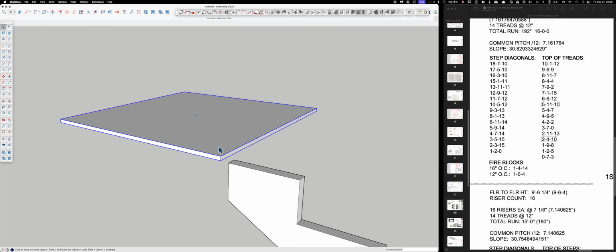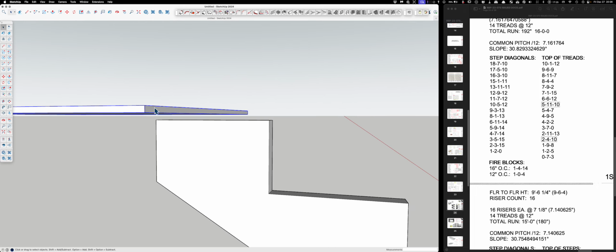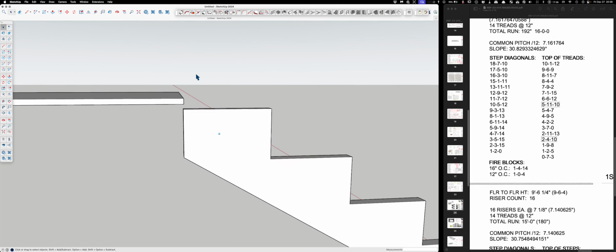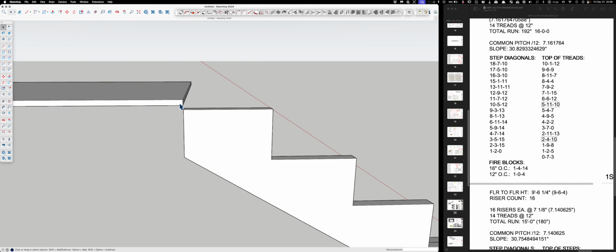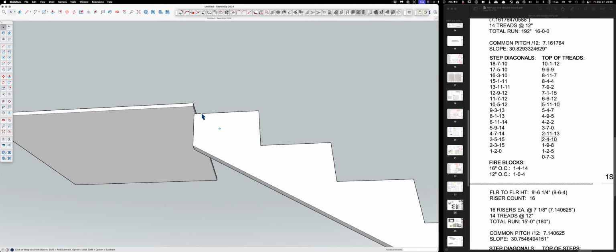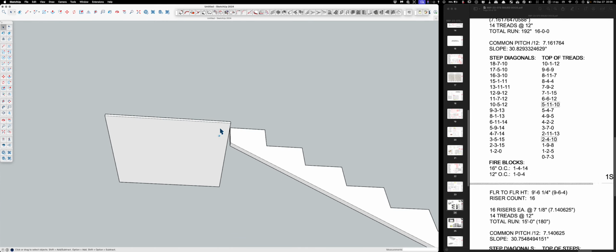So I had enough room to, let's see here, move this way. There we go. So you know what's nice about inferencing? As you start moving, man, it can move in any direction. As soon as you hit one of your arrow keys, it locks it in that direction, and then you can move your mouse around without the object getting squirrely. Let me think about this for a second.